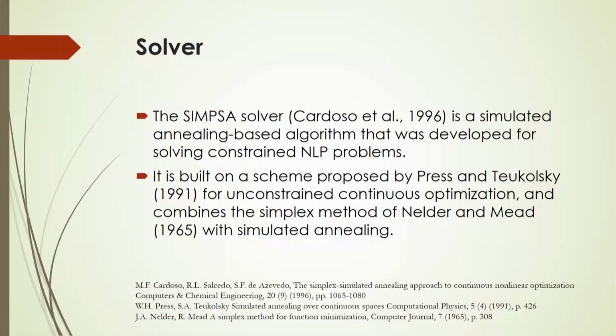What solver can you use for the optimization of this reactive distillation column problem? In this case, the SIMSA solver suggested by Cardoso et al. in 1996 can be used. It is a simulated annealing based algorithm that was developed for solving constrained nonlinear programming problems.